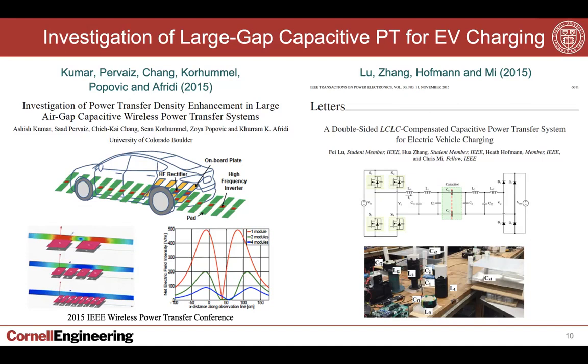And in order to keep the electric fields, which necessarily get developed, and the fringing fields down, which will emerge from the sides of the vehicle, we proposed looking at multiple modules so as to cancel some of those electric fields by having them phased relative to one another. And that was one of the earliest papers looking at automotive applications, or at least where the power was going through the air gap itself and not going through the tires.